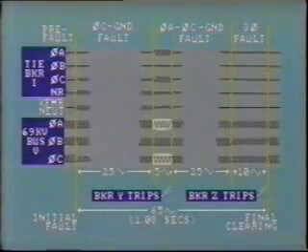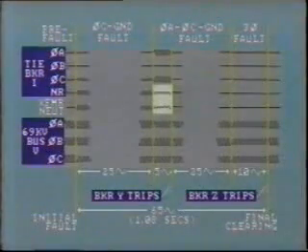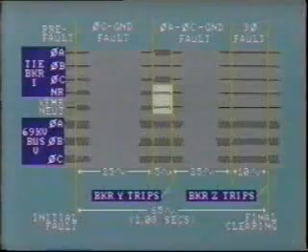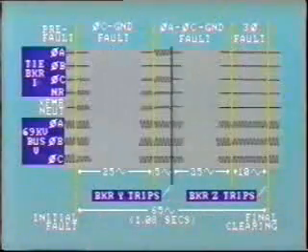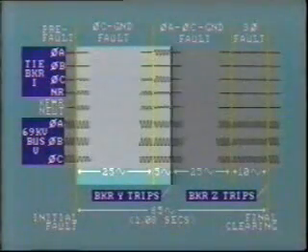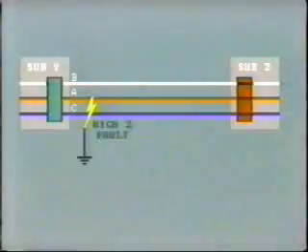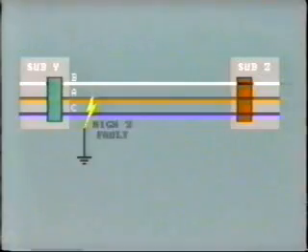Both A phase and C phase bus voltages are depressed. Transformer neutral current and tie breaker residual current are both still present, but they are reduced in magnitude. This is because a double line-to-ground fault is more balanced than a single line-to-ground fault. At this point, breaker Y finally trips to clear one end of the faulted line. The tripping occurs 30 cycles after the initial line-to-ground fault started. This is reasonable since we are dealing with a high impedance fault. Thus, the level of fault current is low, resulting in a relatively long operating time.